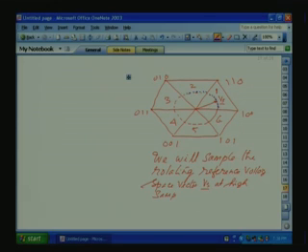When you sample this, the average variation is as close as possible to a sinusoidal. If a continuous sinusoidal variation is required, then we require very high frequency sampling. Very high frequency sampling is its own problem. We have to control the inverter with a very high sampling frequency, so that will also lead to losses. So, there is a limit to how fast we can sample, which depends on the inverter. So, it is a continuously rotating vector, and we sample it with a low sampling period.